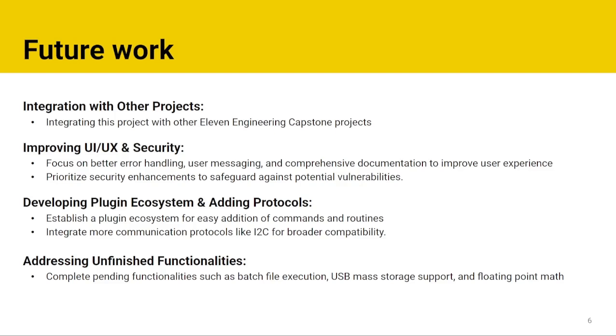Another area of future improvement that extends to the entire board system is to add another protocol or communication method. As mentioned earlier, the board supports UART, GPIO, and SPI, which are all fairly relevant communication protocols. But having an additional protocol such as I2C would greatly extend the board's capabilities and would allow for more sensors and peripherals to be attached.